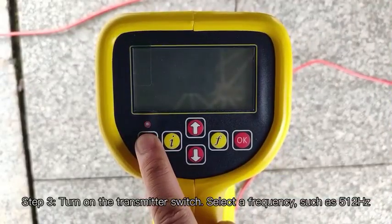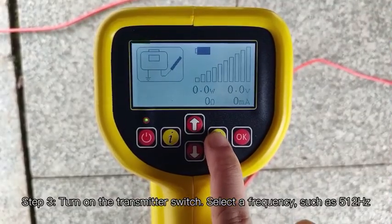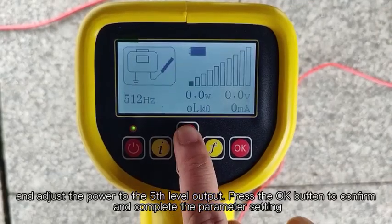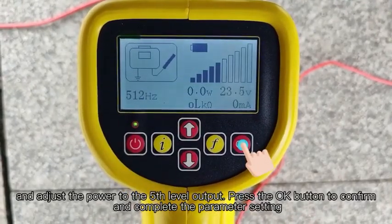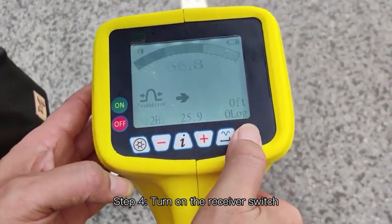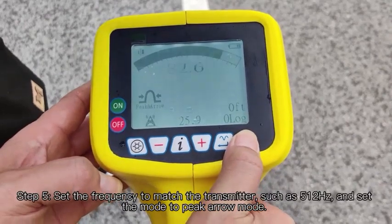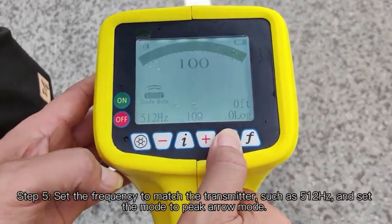Step 3. Turn on the transmitter switch. Select a frequency, such as 512 Hz, and adjust the power to the 5th level output. Press the OK button to confirm and complete the parameter setting. Step 4. Turn on the receiver switch. Step 5. Set the frequency to match the transmitter, such as 512 Hz, and set the mode to peak arrow mode.